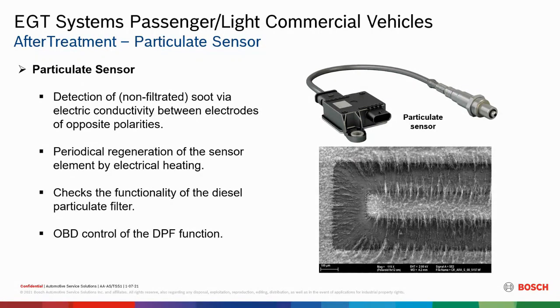So this sensor, again, is a smart sensor. It's got its own module in there, because the signals are so low that if it were distributed all the way up to the ECU, which could be, I don't know, up in the engine compartment while this is mounted in the back, it would lose the signal because it's very, very low voltage. So it's got its own smart signal there. It has that analog signal, breaks that down with an AD converter, brings it to a digital signal and puts it over the CAN bus. It'll deliver that to the modules that are necessary to receive that data.